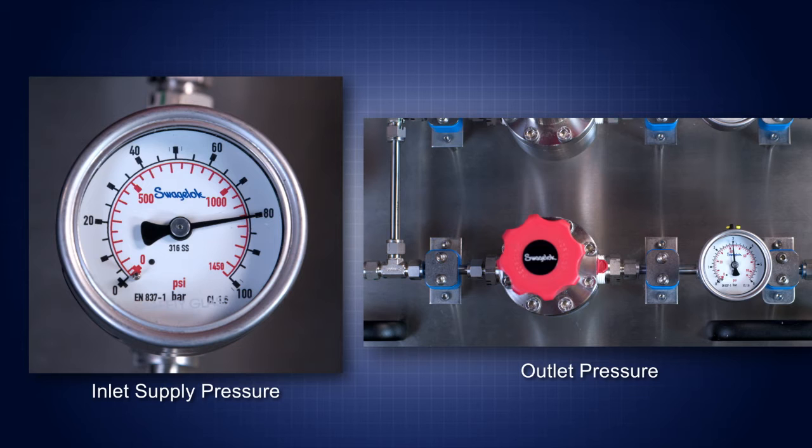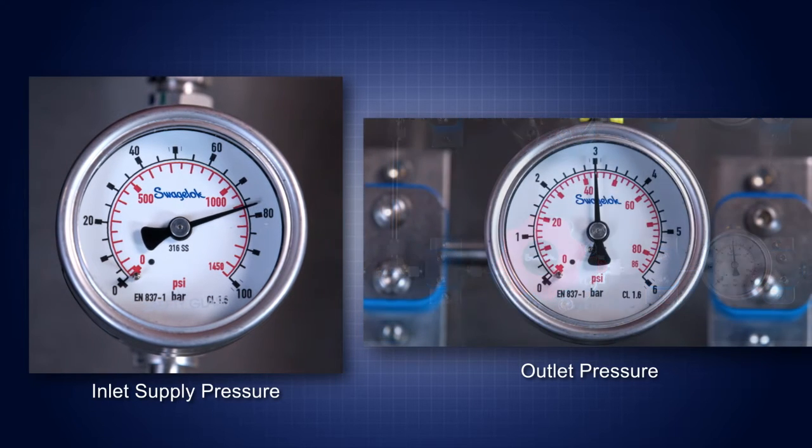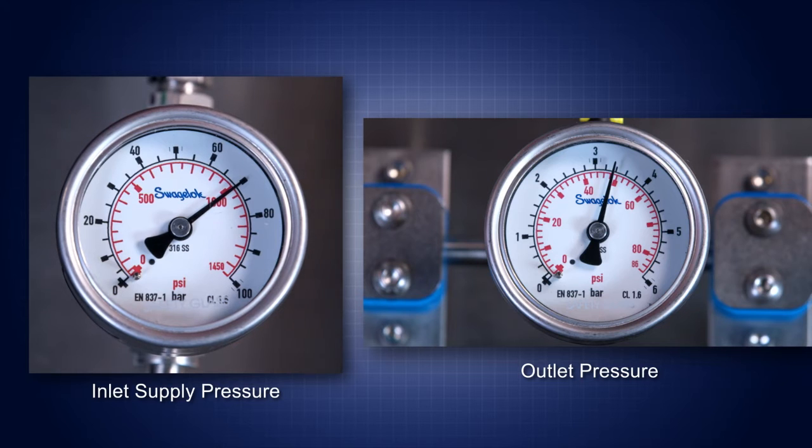As you can see, at an inlet pressure of 80 bar, or 1160 psig, the outlet pressure is 3.0 bar, or 43.5 psig. Decreasing the inlet pressure to 70 bar, or 1015 psig, results in a higher outlet pressure of 3.3 bar, or 47.9 psig. Moving down to 60 bar, or 870 psig for the inlet pressure causes an outlet pressure of 3.7 bar, or 53.7 psig. And finally, an inlet pressure of 50 bar, or 725 psig leads to an outlet pressure of 4.0 bar, or 58.0 psig, the highest of the process.